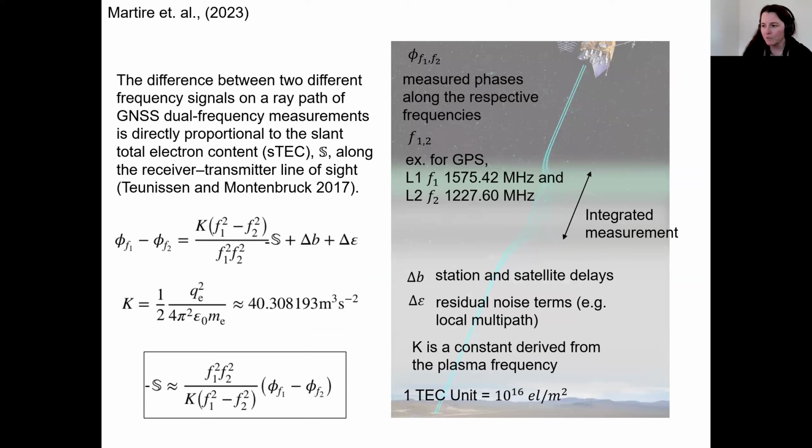These issues are illustrated here. We do see refraction as it passes through the ionosphere. It's not completely lost. We still have the ground receiver retain the signal. But what's interesting and something we can take advantage of is that the different frequencies the carrier phase measurement is broadcast at respond differently as they pass through different densities in the ionosphere.